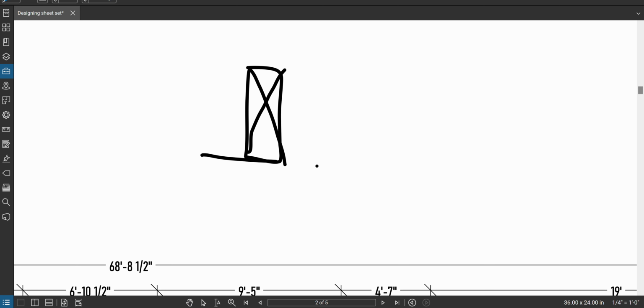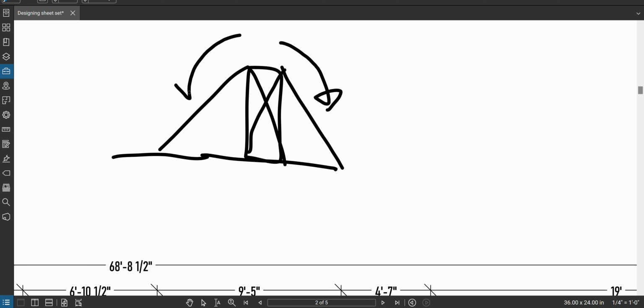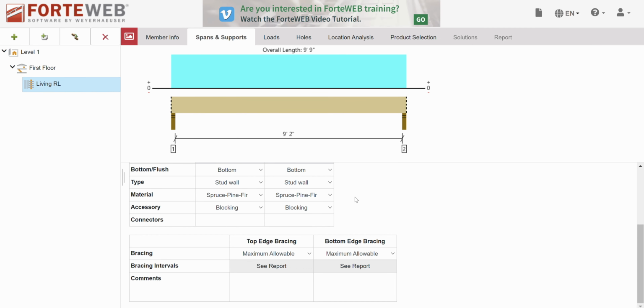When I set it on a wall, I'm going to brace it laterally with some 2x4s or something so that it can't rotate either direction. I'm going to do that on the ends of the beam. That's what that's referring to. It's called blocking, and typically blocking is done with blocks. In this case, they're just used in a different way. But the premise is that you are preventing the ends of the beam from rotating by restraining them. So we're going to leave blocking on because that helps us. It makes our beam stronger.